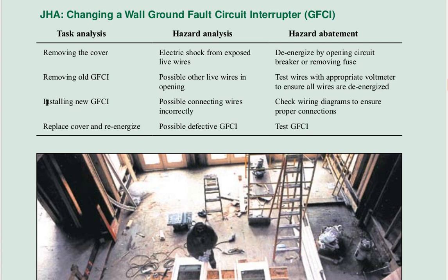The next task, installing the new GFCI. Hazard analysis. Possible connecting wires incorrectly. The hazard abatement. Check wiring diagram to ensure proper connections. The next task that you will do, replace cover and re-energize. Hazard analysis. Possible defective GFCI. Hazard abatement. Test GFCI.